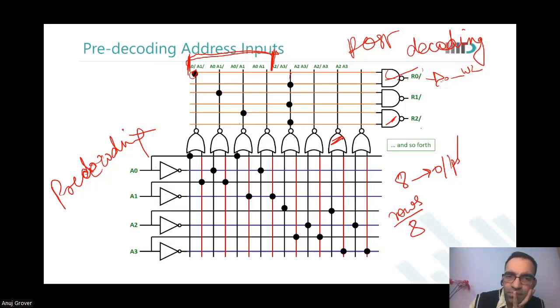Sir, there are 3 connections to the row for 3 AND gates. So at the same time, 3 AND gates would take the input from that fifth NOR. So would it create any kind of race condition or would it increase the capacitance load on the fifth NOR output? So see, how many row decoders will that gate 5 be connected to in total? Sir, is it 4? Yeah. So total it is 4 only.